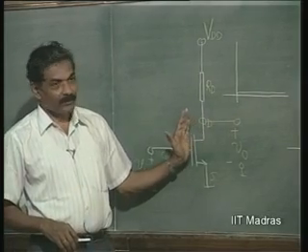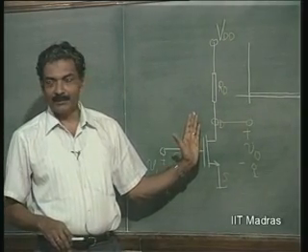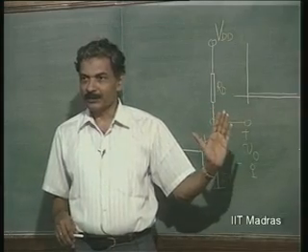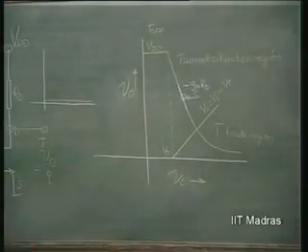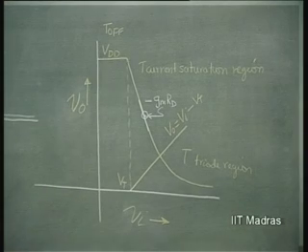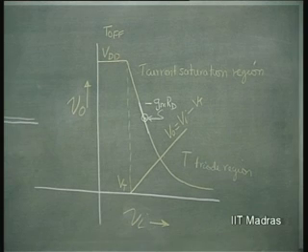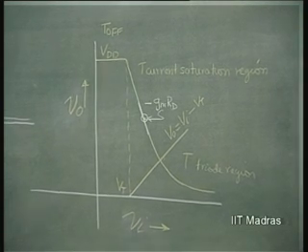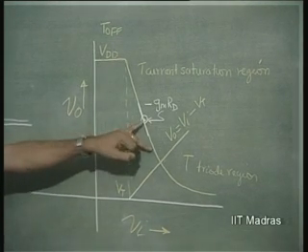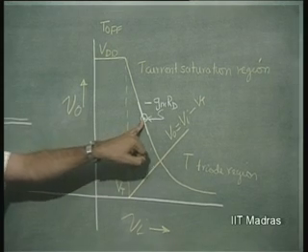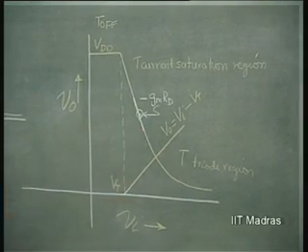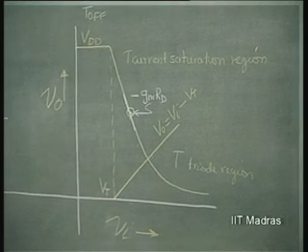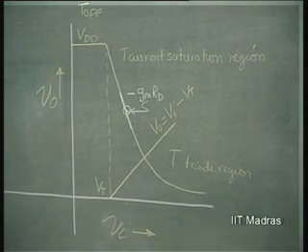and therefore, the equation to be satisfied is that Ids is equal to k times Vgs minus Vt whole squared, and using that information we could get the slope of this characteristic as minus Gm into Rd, where Gm was equal to 2k into Vgs minus Vt, Vgs being Vgsq, the quiescent voltage here, which is Vgsq or Viq. So, that slope corresponds to Gm into Rd, it is negative, indicating inversion.